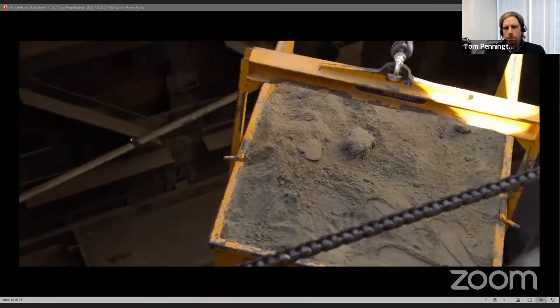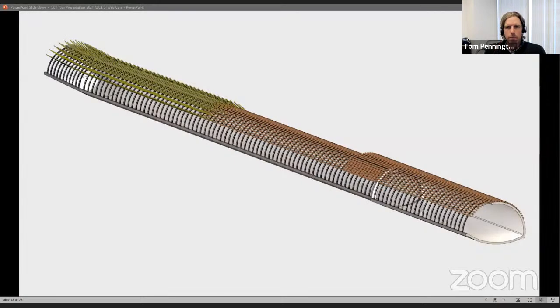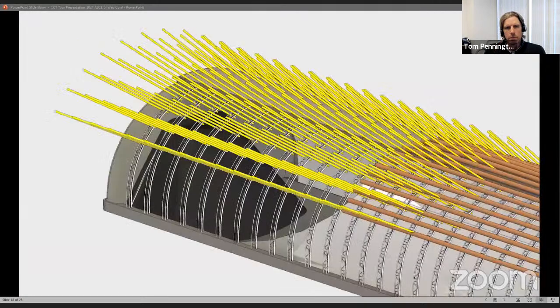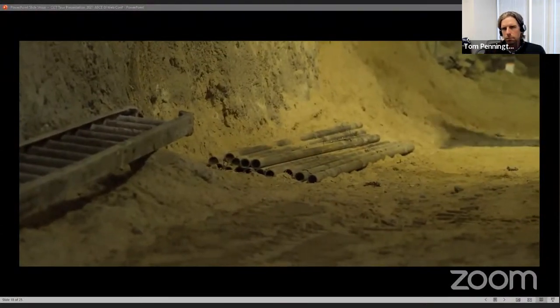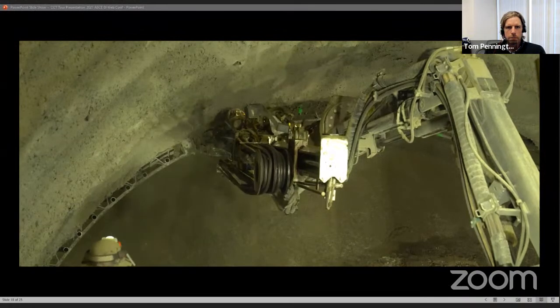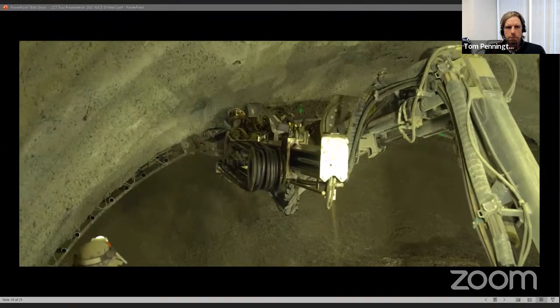Once past the area of the canopy pipes, a different pre-support method began: pipe spiles. The installation and grouting of an array of 24 hollow pipe spiles, each measuring 12 feet long by 2 inches in diameter, became a required step in each excavation round.